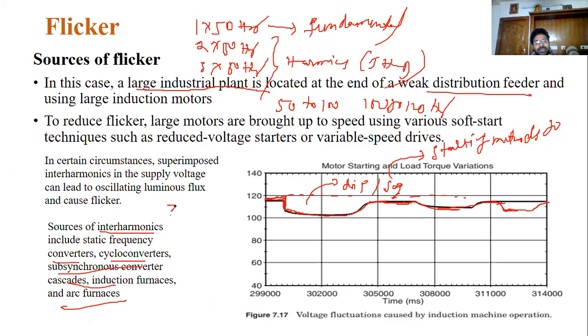At the same time, another one is also there: electric arc welding. You observe that whenever you go outside to a welding shop, when they weld the iron, you can observe the lights in the shop change the illumination. That is flicker. You can observe that practically many times. A few days back in my house also, I observed flicker because of heavy rain at that time.